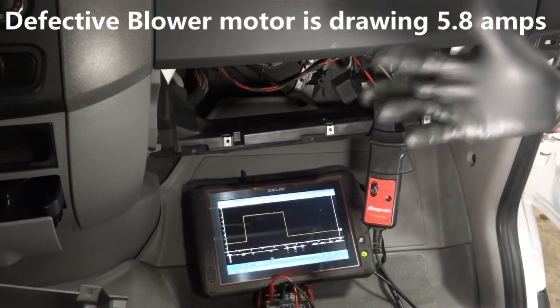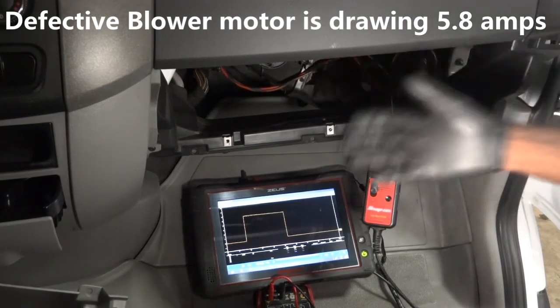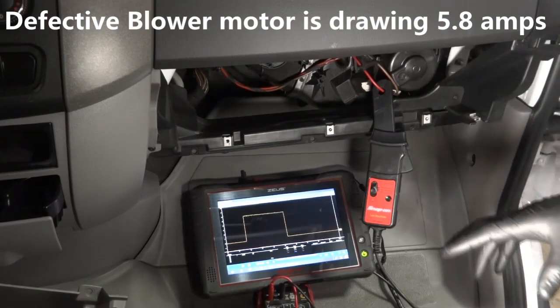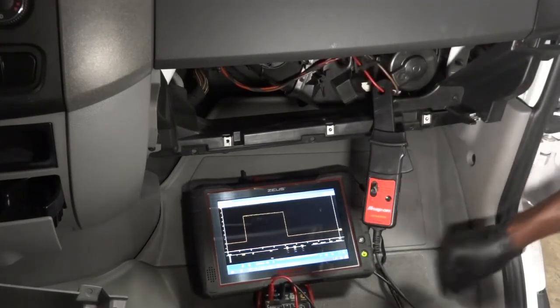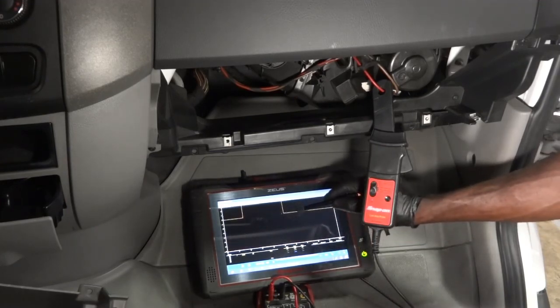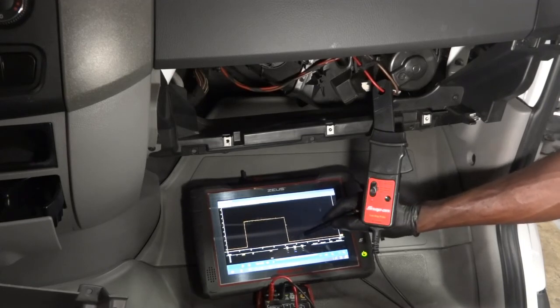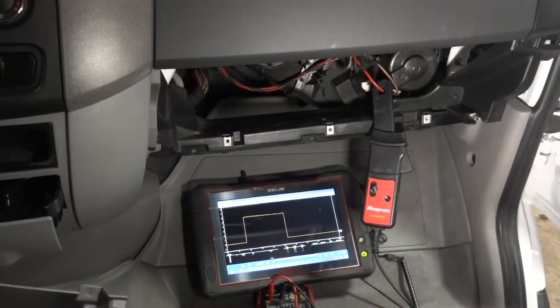The test that we did with the test light was definitive enough. I wanted to bring the lab scope into the picture so that we could see how much current the blower motor is drawing. And we're also going to do the same thing with the new blower motor. I believe the new blower motor is going to be more of a gradual increase in current than an immediate increase as this one is doing. Okay, so shorted blower motor.